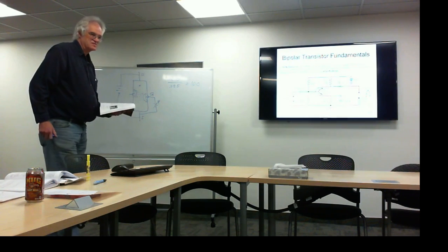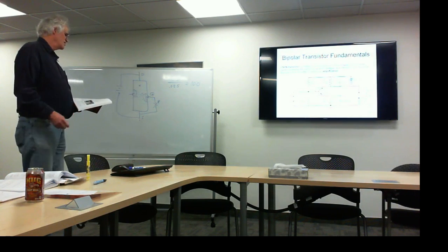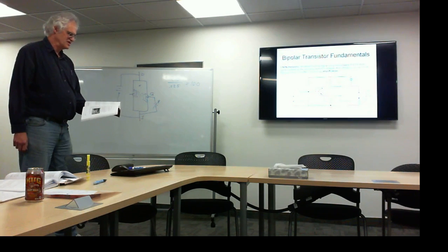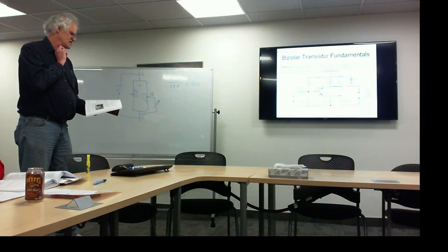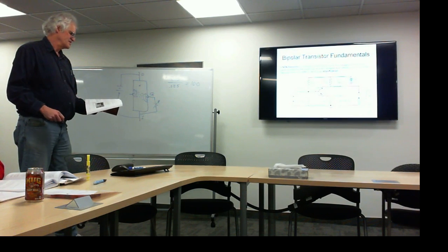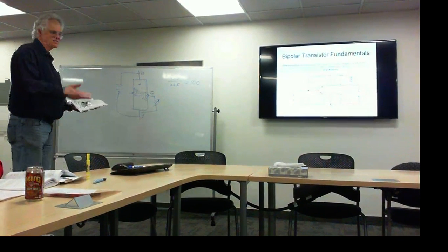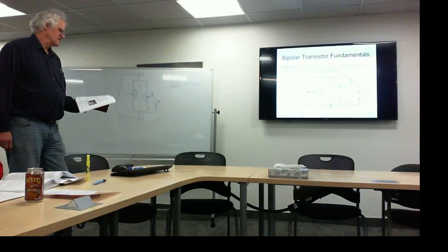Alright, and again, as we were talking about before with diodes, carrying it a little bit further, some of the characteristics or specifications for a transistor. They talk about a breakdown voltage, which is basically the maximum voltage you can apply between the collector and emitter or any of the terminals without doing damage. And they also talk about maximum current, the actual maximum current that you can pass from the collector to emitter without damaging it. And the maximum power is how much it can handle.